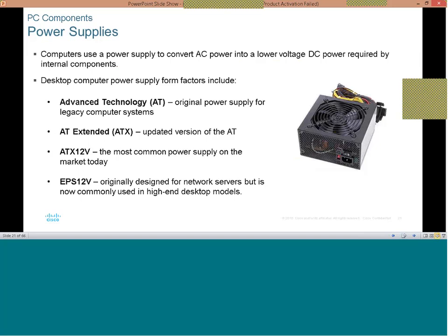What you have coming out at the different ends of these cables are rated in DC volts. So what goes in is AC and what comes out is DC. If you look down here, you see a red button. This red button is a switch that you can use to switch between 220 and 110 volts.